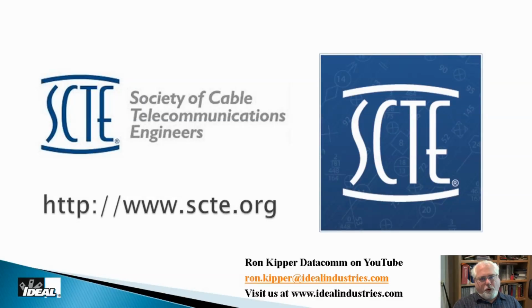Now, when you talk about coaxial cables and really any type of communications cabling, that cable is made to a certain specification and is designed to perform at a certain specification. When you hear the term RG associated with coax, it refers to radio grade or radio guide, depending on who you want to argue with. It's actually an old military specification. You should be aware that all these cables should be working at a certain capacity, so to speak. And a lot of cable we get today, while it might say it's RG6, is really not military spec cable, but something less than that.